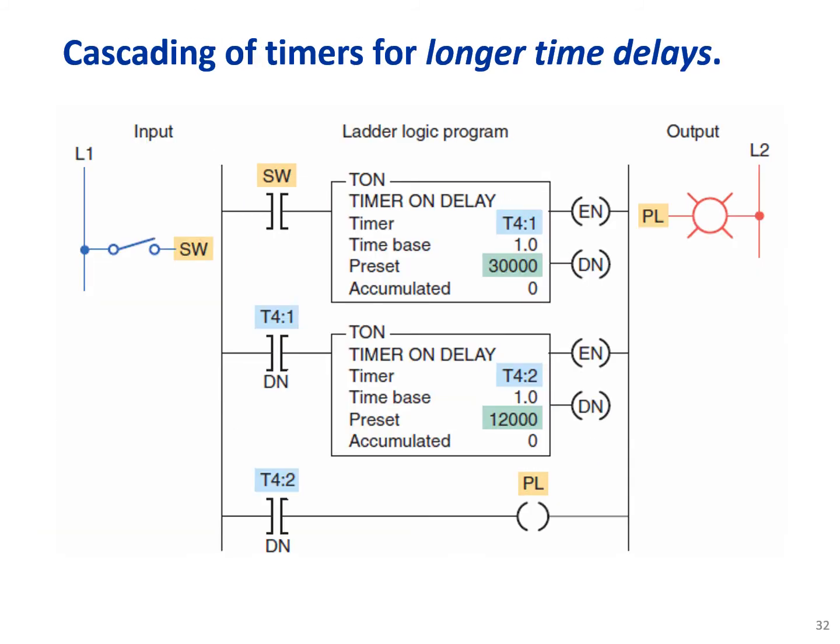Cascading of timers for long time delays. In some PLCs, I mean hardware, you have some limitations in terms of using timers with high preset time values, and then you have to go with cascading timers for longer time delay.